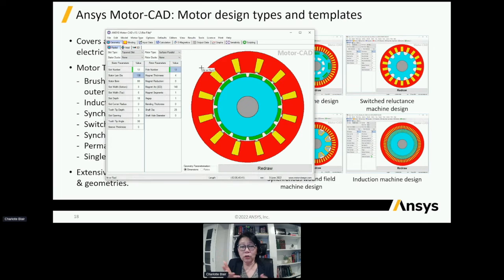We're looking at the physical geometry. Make sure that electrically it's drawn correctly. This may be a big part, and this is low frequencies. And for those of us in the audience who are more high frequency, and we're looking at printed circuit boards, maybe that via, whether it's filled or not, and maybe if that ground plane is placed close to a signal trace, does it matter electrically? Yeah, it does. Or maybe the manufacturer says you can't make the spacing between the signal trace and the ground plane only 10 mils. You need at least 50 mil clearance.